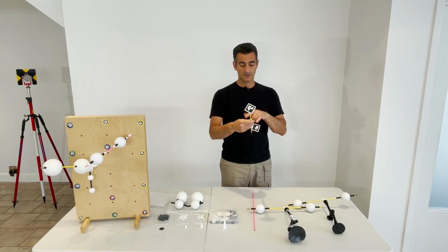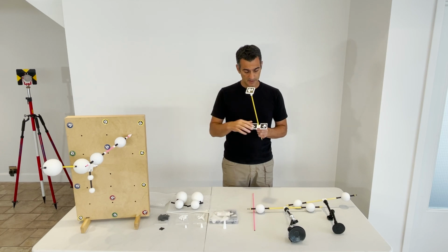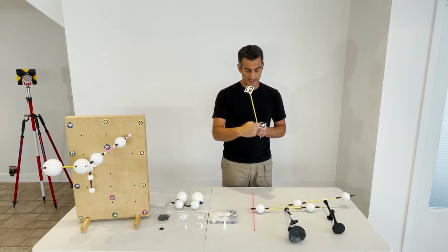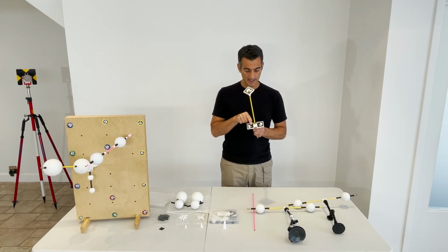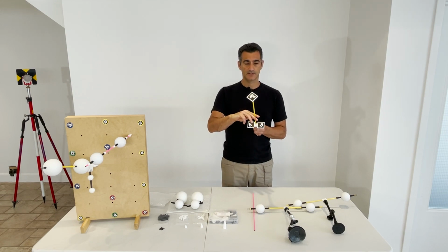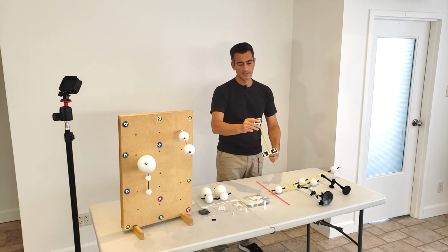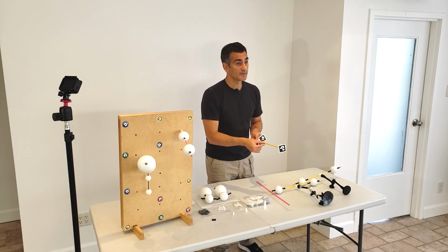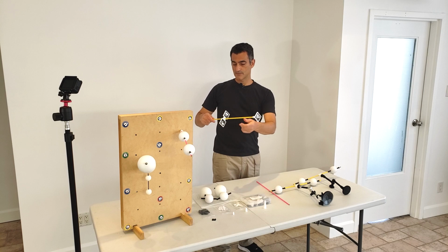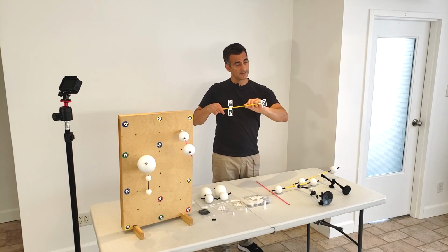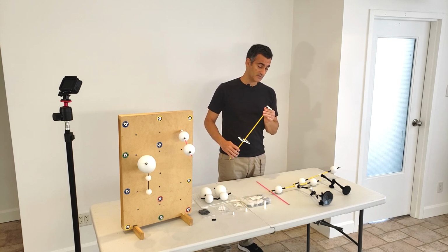But basically here we have 2 targets, and the center of these 2 targets we can determine through the software. So we have a center point and a center point. If I connect those 2 points, that line will run through the center of this point. So the midline of this line is right through the center of this trajectory rod. That will coincide with the center of this particular target here, and the center point there should align with this trajectory rod. And so it's pretty easy. You can put this on the trajectory rod, take photographs, and then instead of trying to detect just the rod, you can detect where these targets are. So that's useful as well.